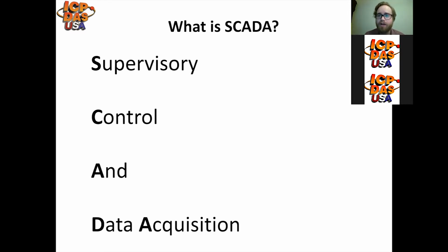You might have a bunch of legacy serial modules, some newer Ethernet modules, PLCs, automation controllers, PC-based controllers, and regular PCs or industrial PCs. What SCADA does is strive to integrate all of those control and data acquisition systems.